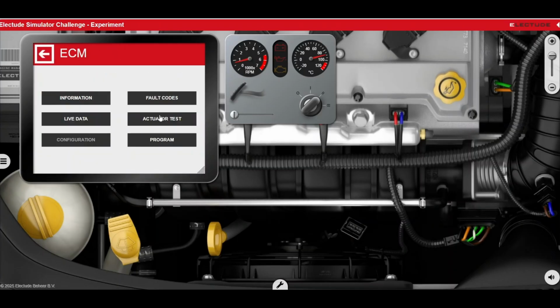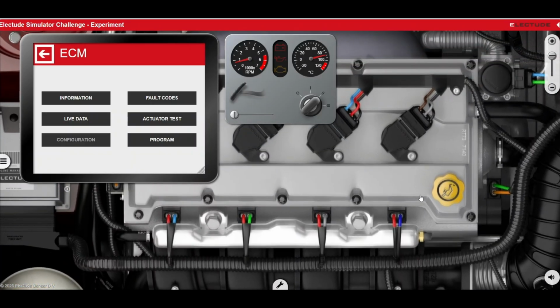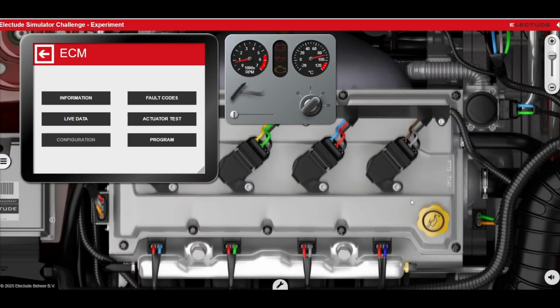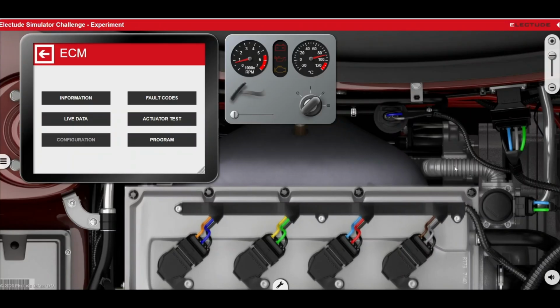Not yet. I think it will check the circuit when it wants to, when the engine warms up enough and the computer wants to turn on the fan. That's when it will store the code. The same thing for the evap system.